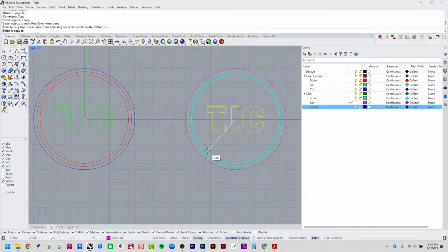To find that center, all you need to do is enable OSnaps, enable that center OSnap, and then navigate to the edge or a near point along that piece of geometry, and it'll almost always identify its center. Once you see that little verbiage right here, CEN, center, you can go ahead and click and rest assured that it'll move it to that center.